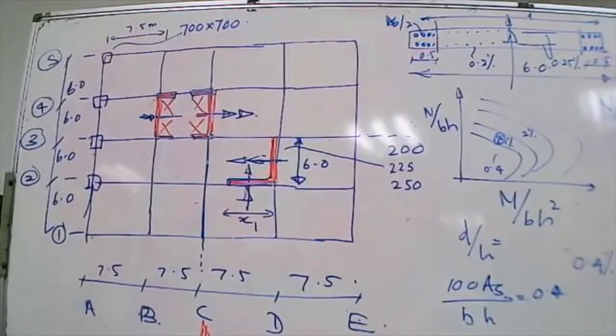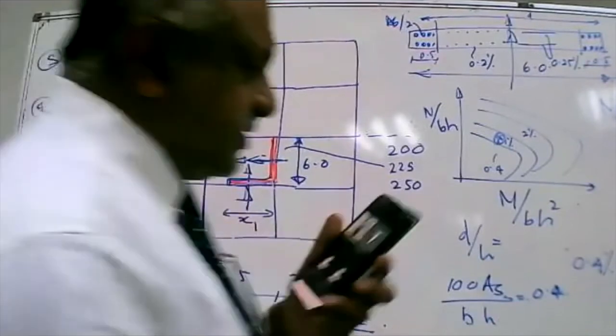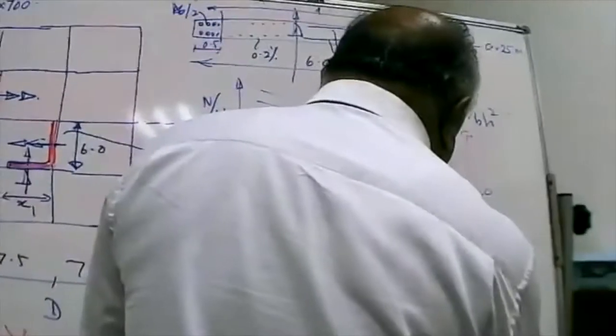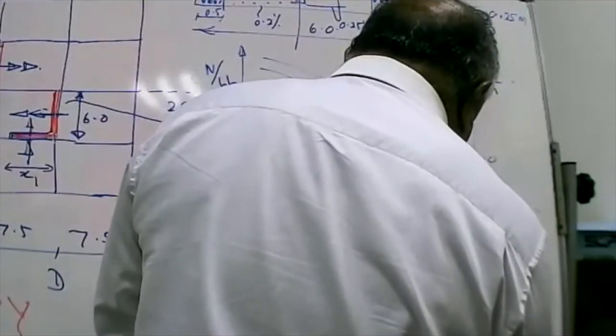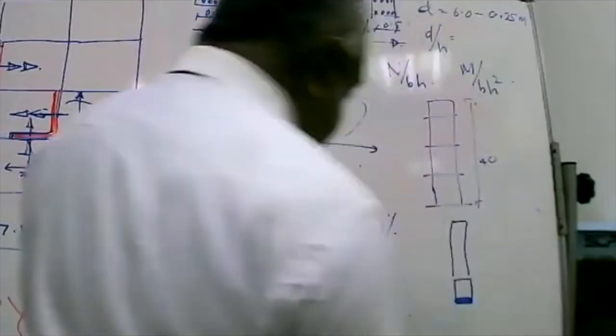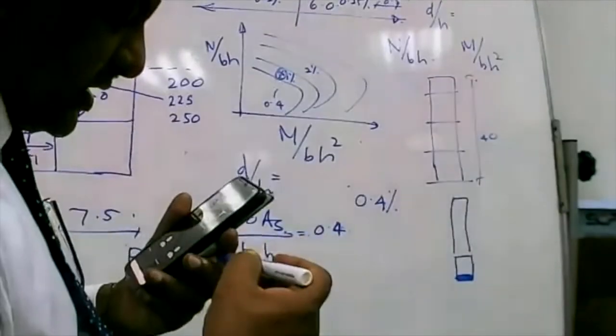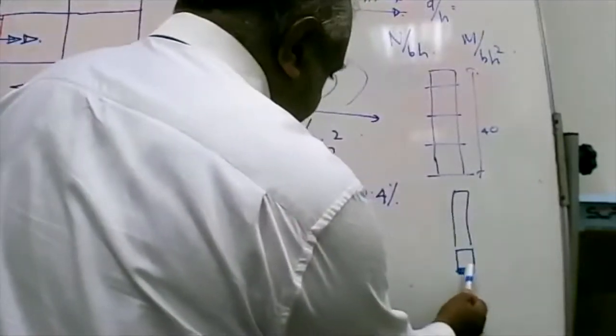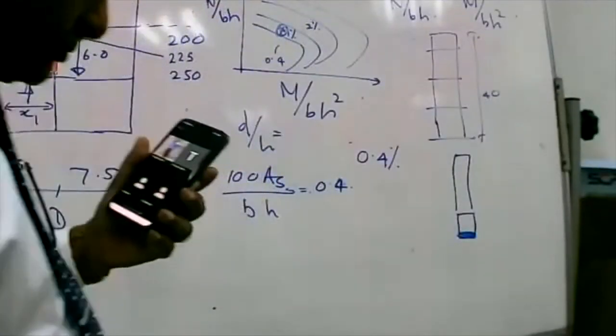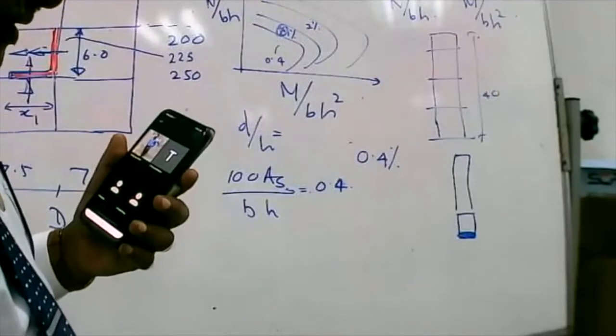So if you have lightweight partitions, there's a good chance that a raft foundation may be possible, but you might have to consider a weight compensated raft, where the building will have 1 or 2 basements, and the bottom slab of the basement will act like a raft.